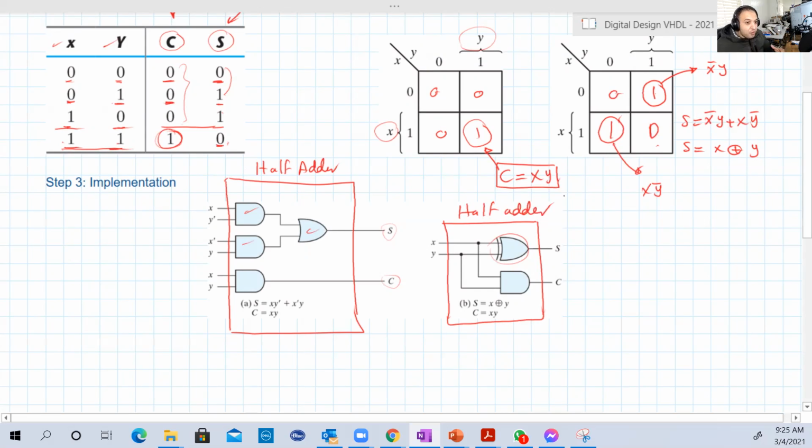Now, before we go forward to our next topic, let's explore one disadvantage of this circuit. So let's do a normal addition, something like 11 plus 11, which is 3 plus 3, which is 6. Okay, make it like this. So in here, let's add these together, just like our chapter 1. So 1 plus 1, these are 2 bits, so we can here do a half adder. 1 plus 1 is 0, and we have a carry of 1.